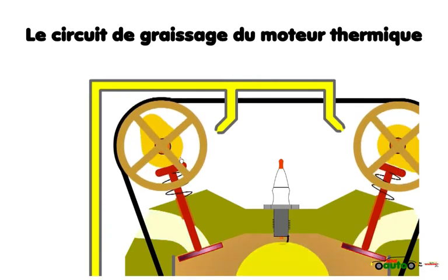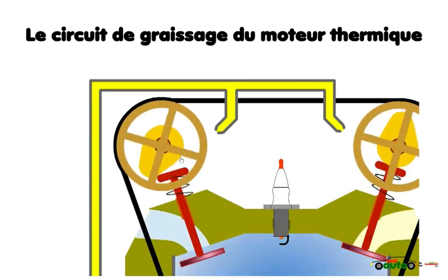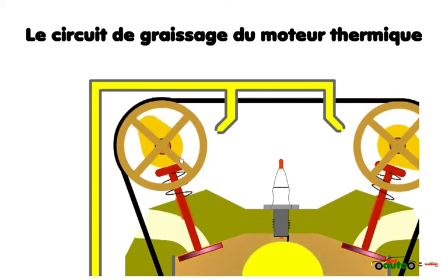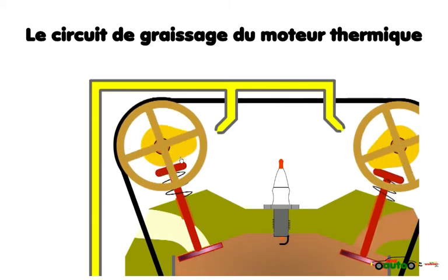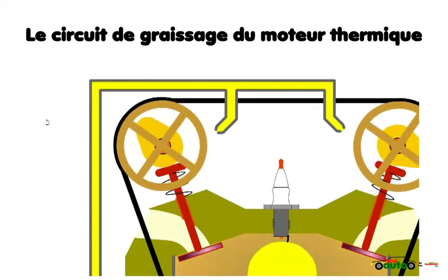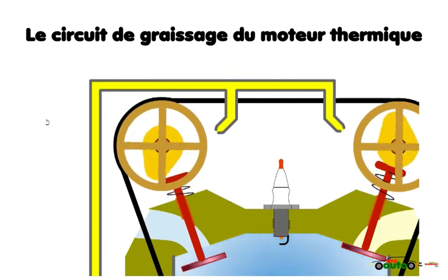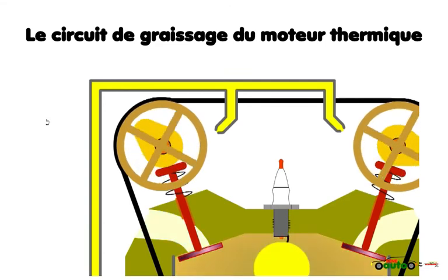In the past, the ventilation was vented to atmosphere, but this was considered a source of hydrocarbon emissions. The PCV positive crankcase ventilation system routes combustible gases to the intake manifold where they are burned, thus reducing emissions and preventing overpressurizing of the engine.